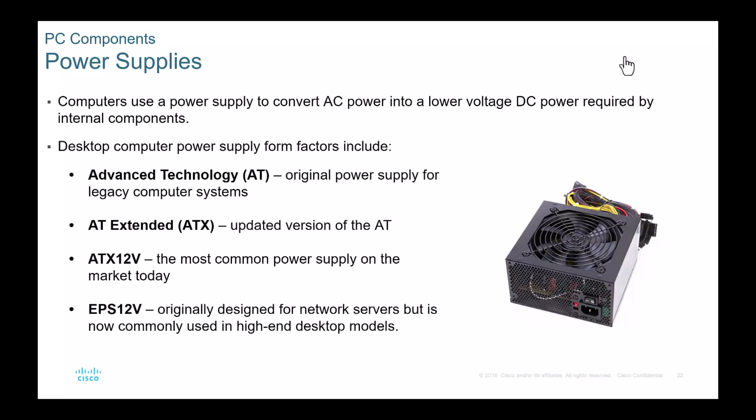You see more of the ATX, the 12 volt. That's what you see where you have the modular cables, the thinner cables. You don't have some of the old dated things on there, like the floppy cables, or you still see some of the 12 volt Molex cables, but they are a lot more streamlined for what is needed today. On your AT and your ATX, you probably wouldn't see your video card power cables, because that's something within the last couple of years where we needed more dedicated power for those video cards.